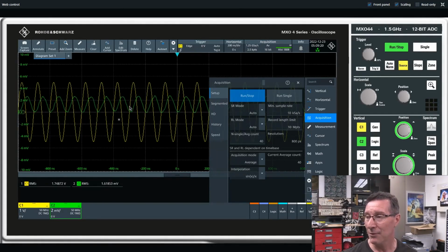But you can see how we are dealing with the wobblies down here, because as I said, the test setup is everything. If you can shield it and keep the leads short and make sure that they're twisted and everything else, it's going to be better. But let's see if we can use this to get our figure. So what we need now is to compare the input signal to the output signal. That'll give us our common mode rejection ratio.